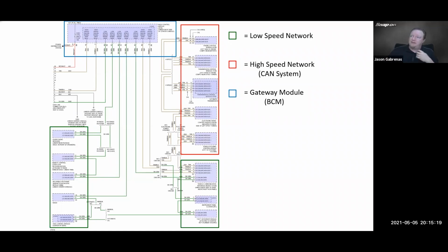So they went down the list, couldn't communicate with the engine, couldn't communicate with the transmission, couldn't communicate with the brakes or the power steering. But once they got down to the instrument cluster, airbags, radio, all of those things, he was able to communicate. Also couldn't communicate with the body control module. And he said, "Well, that's weird. I can communicate with half the car, but not the other half.